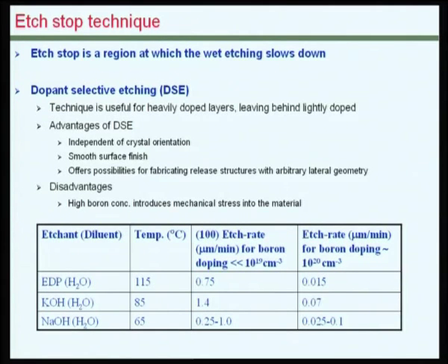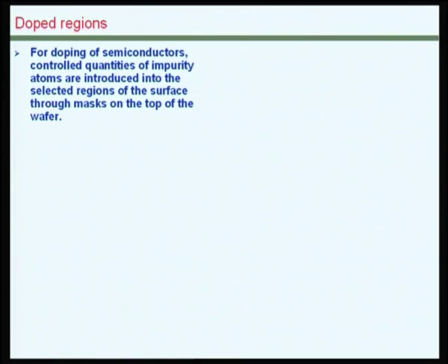This feature can therefore be utilized for realizing a flat uniform thickness membrane, for example for pressure sensor applications. As I mentioned, this would require doping.